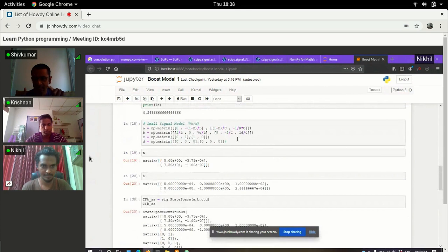If you had just a one row array, it's like this: C sI minus A inverse into B. If C is 1 by 2, sI minus A inverse is 2 by 2, and B is 2 rows in one column, then the result will be one single polynomial.